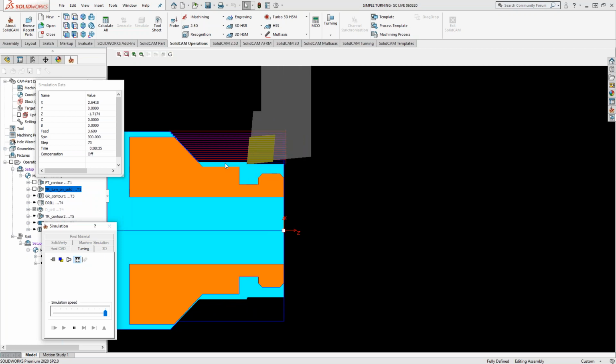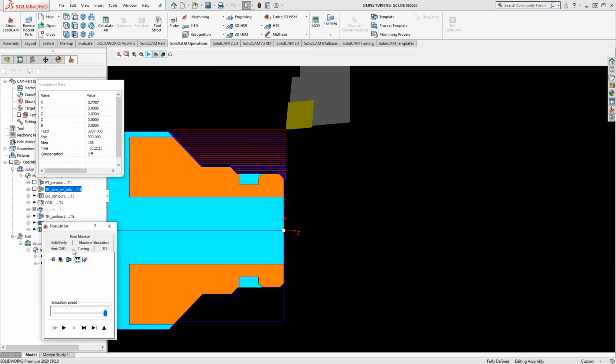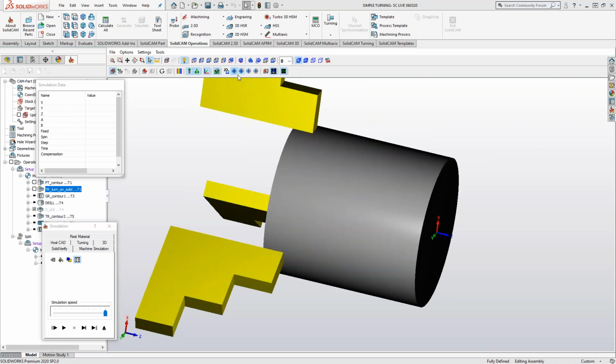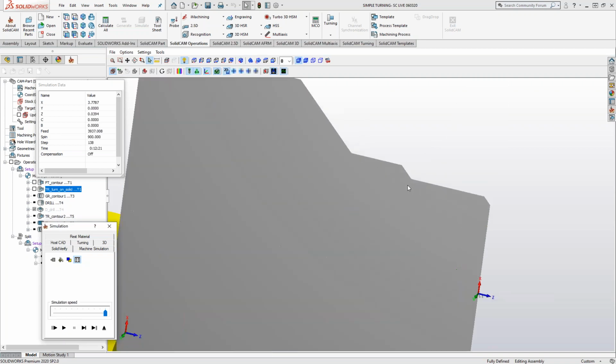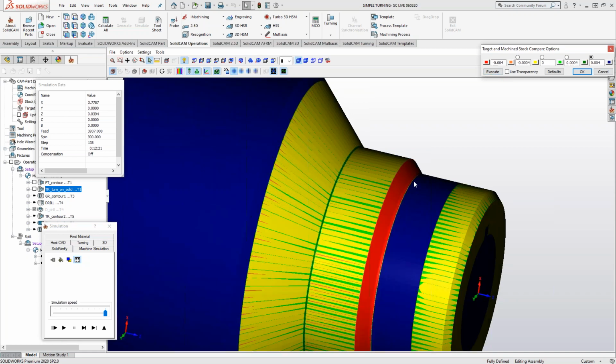And then as soon as it gets there, you'll see that it starts to form the chamfer. Now this will count as a gouge, obviously. If we go into Solid Verify and run that again, let's just get that 2D representation there. It added the chamfer, and put this back to solid. But if we run the gouge check, it counts as a gouge.